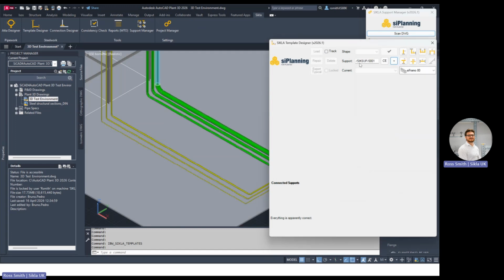And then since this is now active as our CE, this is an Aveva language, so current element, it means whatever is selected. Okay, we can then use the templates to build a secondary support. So what we want is this shape, so something like an H-frame, or we call it a goalpost, and I'll select this. And then once we do select, we then have tooltips appear on the end of our mouse and also down in the command line.